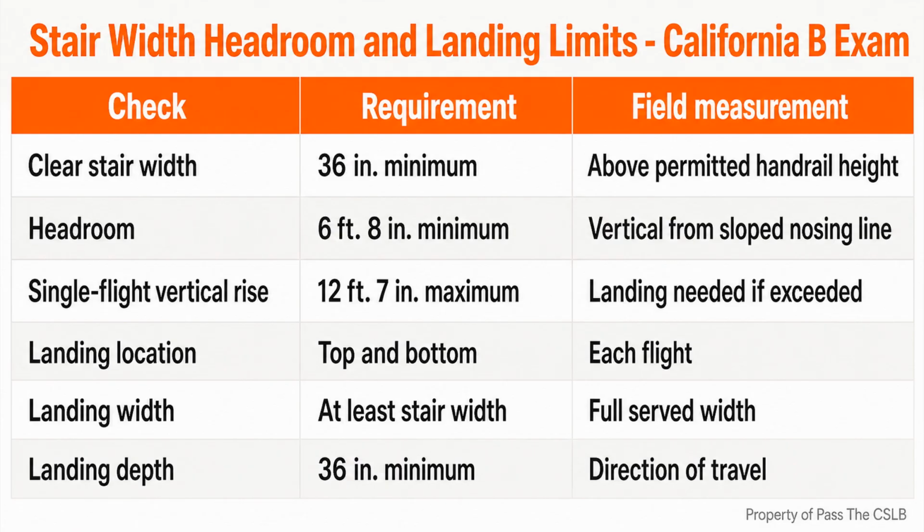Here is the consequence chain. A missed finish thickness changes one end riser. That end riser may exceed the variation allowed within the flight. The stair may then require adjustment or rework after expensive finish material has already been installed. The problem begins as a layout detail, but it becomes a schedule and quality control problem.